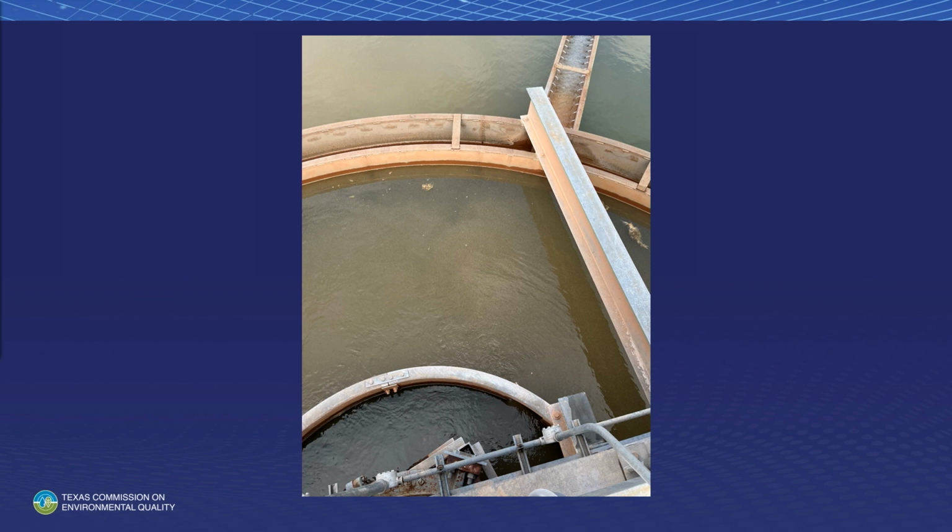Everybody understand what a serpentine flocculator is? I'll bet none of you in here are old enough to have ever seen one. It's just a channel that goes down and then makes a turn and comes back and then makes another turn and goes down and makes another turn and comes back. And that hydraulic mixing going up and down those channels is what provided the flocculation for them in the older designed water treatment plants. Another solids contact upflow clarifier that was full of sludge.